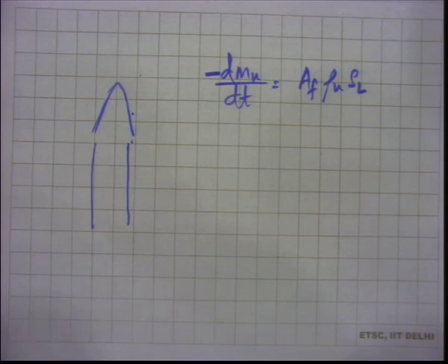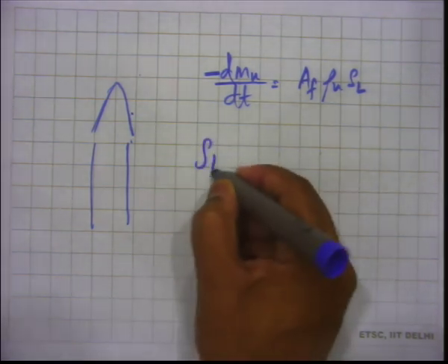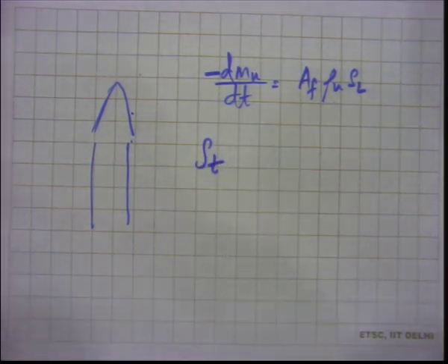Okay. So, that is extremely important, but how do you do it for turbulent flames, because the area is going to be a problem. Which area? All right, because the area seems to be fluctuating all over the place. So, that is one problem. The other thing is that how do you at all define turbulent burning velocity? Turbulent burning velocity can be defined similar to laminar burning velocity, in the sense that it is that velocity with which the unburnt mixture moves into the flame relative to the flame, normal to the flame. If you can do that, right? You can say that,